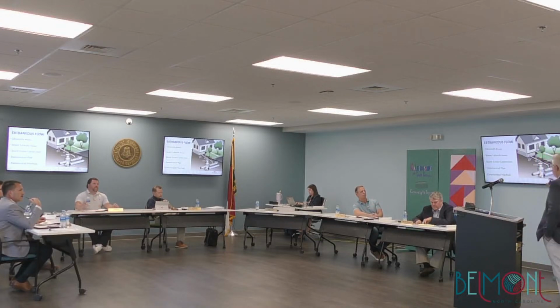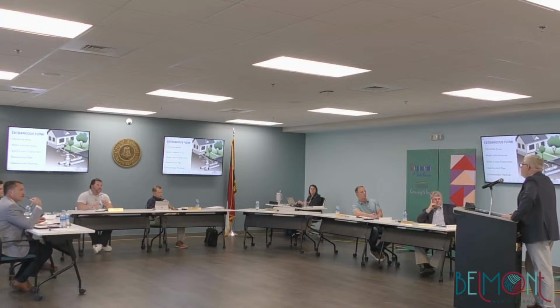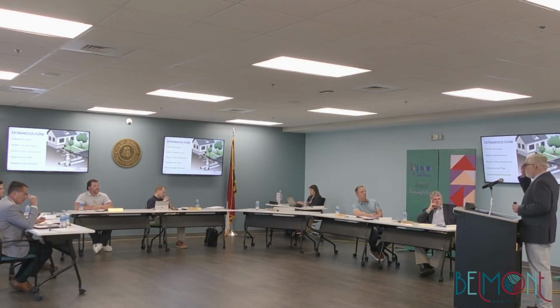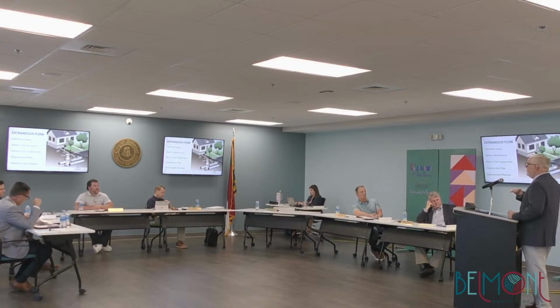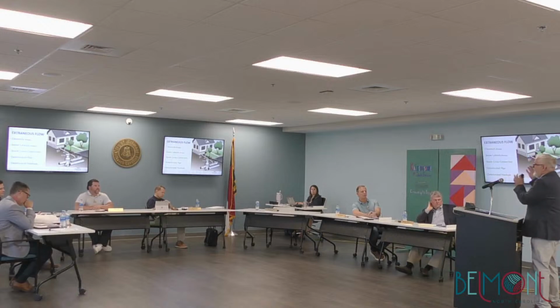No, so there was a chart that I had, and I pulled it out of this deck because I didn't want to get too deep on you here. But in some of these events, put it this way, on a dry day, a day like today, this pipe may have, I'm just going to use some random numbers for example, so it's specific, okay? Let's say that it's got 10,000 gallons flowing through it during the course of the day. During a rain event, in some of these cases, we're seeing these pipes have over 100,000 gallons of water running through it. So it's 10,000 gallons tributary, 90,000 gallons of groundwater. It's that level of magnitude.